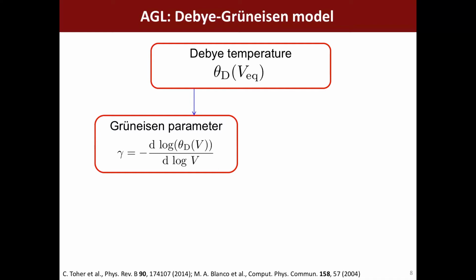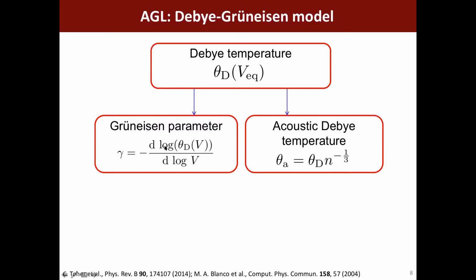So if you have a perfectly harmonic crystal, this energy volume curve will be a perfect parabola, which means that its second derivative, if you think of it, so this was what the bulk modulus was, will be a constant because it's a quadratic. But in real materials, this is going to deviate from a perfect parabola. So you're going to have some anharmonicity. And this is what gives rise to things like phonon-phonon scattering. It gives rise to thermal expansion, all these types of properties. And so this is quite important to estimate these properties.